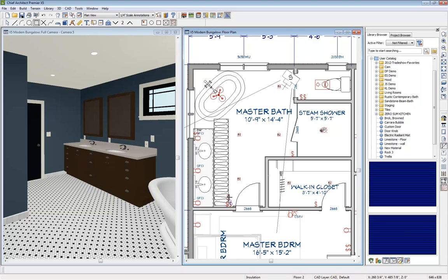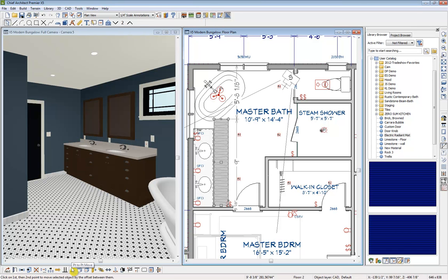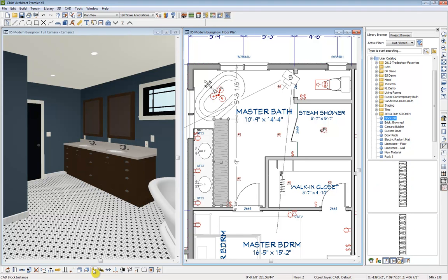Since this is the standard mat that I will be using throughout, I want to make this a CAD block. So I'll marquee around our items here. Just click and drag and marquee around all those items. And at the very bottom, we'll have a Make CAD Block option. Single click, and now all of those lines are blocked as one unit, and we can add that to the library. So we can use that for further use, and you can also rename that as you need to.